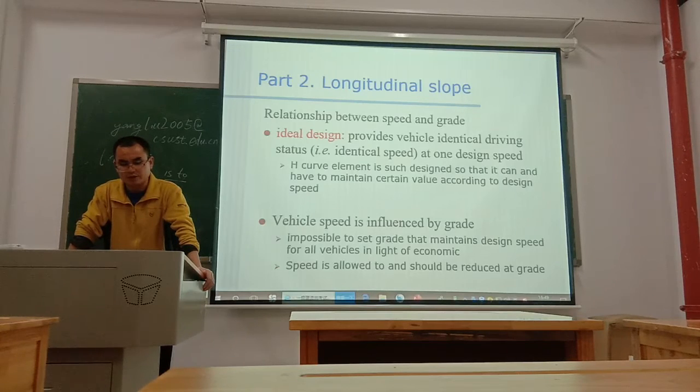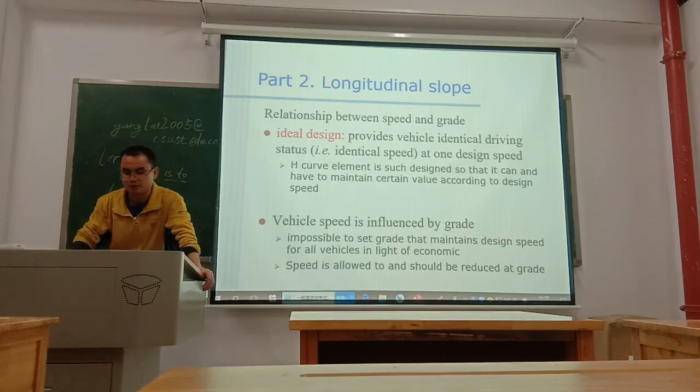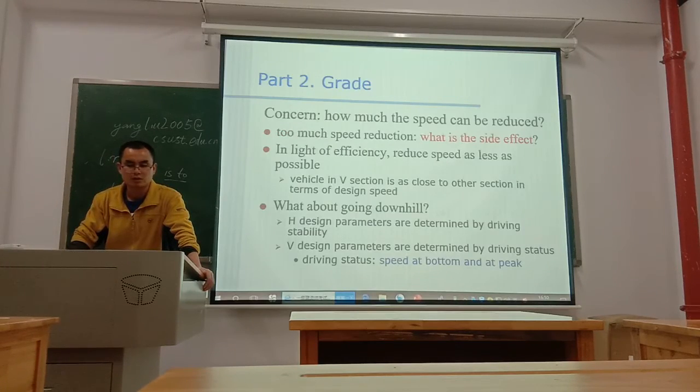Vehicle speed is influenced by grade. It is impossible to set a grade that maintains design speed for a vehicle in light of economy. Speed is allowed to and should be reduced at grade. Can you say how much the speed can be reduced?